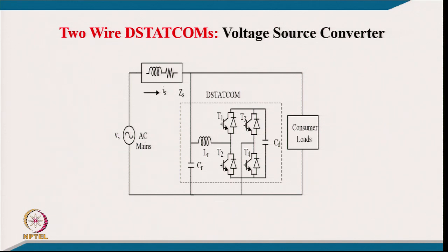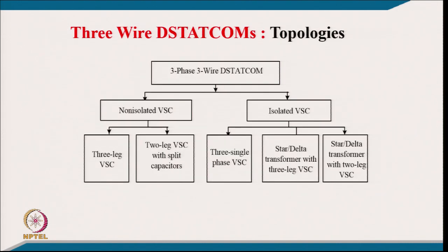So, the entire ripple voltage has to be absorbed across the inductor, and for the fundamental frequency this capacitance has very high impedance. So, it will not draw any fundamental current; the current into the capacitor will be very small. Sometimes we even put a small damping resistance in series. So, losses are also negligible in that case, but it improves the voltage profile at the point of common coupling, which is affected because of the switching of this converter.